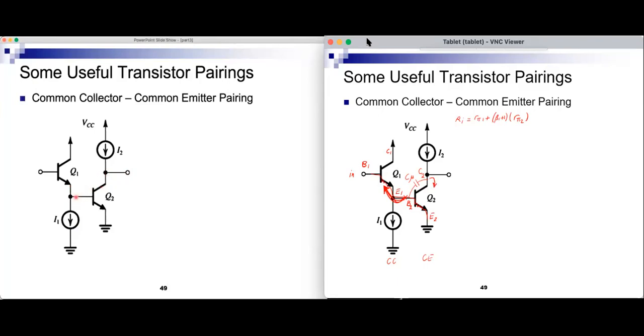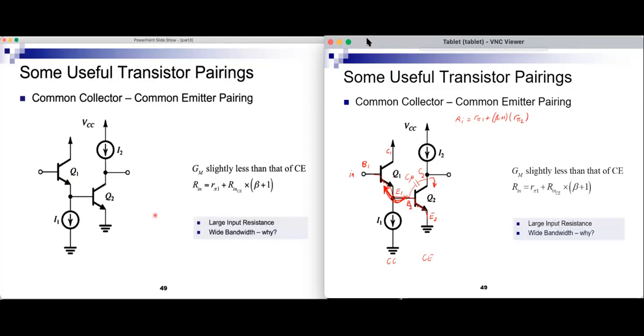In the case of Q1 connected here, R x becomes very small, and therefore R x y becomes very small. And R x y multiplies the capacitor to give us the time constant. So if all of that is small, omega h will be 1 over small and therefore a large bandwidth. So this amplifier has the advantage of a wider bandwidth than common emitter.